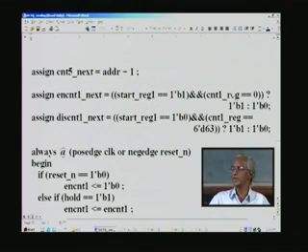When these conditions are met, then only will we enable the first counter, and the same counter is disabled if the last of the block is processed. For example, start has become 0, and in that case, when the counter value is 63, only then do we disable the counter. Otherwise not. Note that it is for 0 as well as for 63, not any other combination.